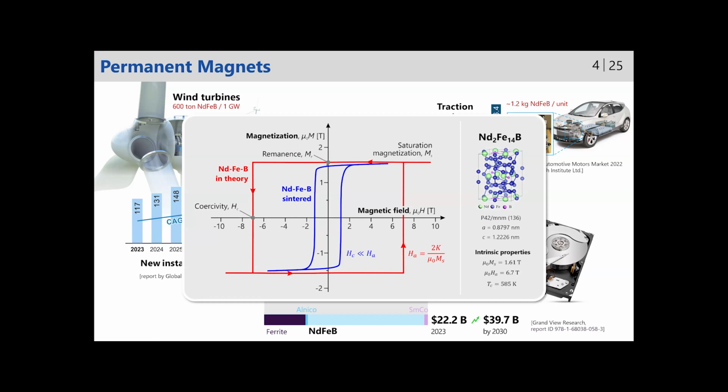For example, neodymium 2 iron 14 boron: a reliable list of all intrinsic properties, starting from the anisotropy constant, exchange stiffness, saturation magnetization, and so on. And for other phases, also secondary phases. Quite often, we don't know exactly the magnetic properties of some phases. That's why we should try some approximations of experimental data in order to estimate them.